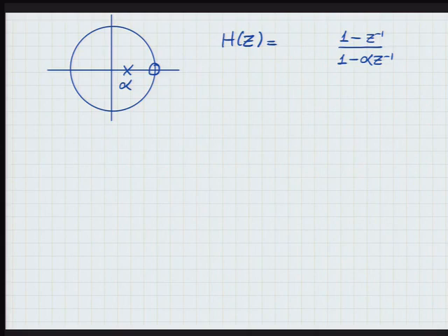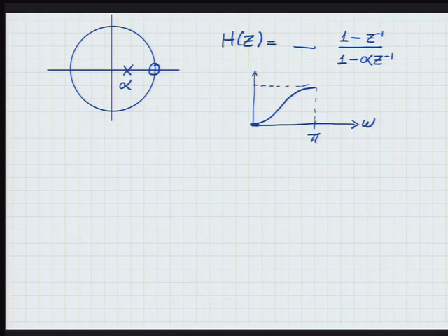All right? So when we put it in this form, of course, I'm going to need a coefficient here. How should I select it? The frequency response I'm expecting now is going to start at 0. Why? Because we have a 0 at 1. And then it will increase. And I know it's scary. I would do the same. Okay, so we want to pass high frequencies, so a unit gain there is appropriate. To make that happen, how should I select the coefficient?